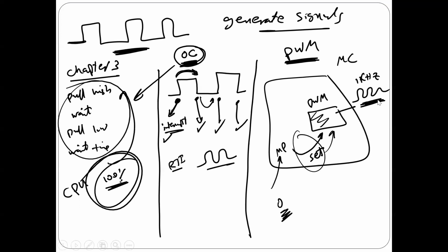So here's the difference here, guys. The microcontroller is involved here for interrupt. For sure, that's much better than this one, for sure. But still, here in every transition from low to high or high to low, there is an interrupt. In this interrupt, I have to write a couple of commands to set the next toggle, when the next toggle is, right? So I need here in every transition a little time from the CPU. Here, once you do the initialization, the signal is going to be generated forever until you decide to turn it off, with zero time from the CPU, without the intervention from the CPU.